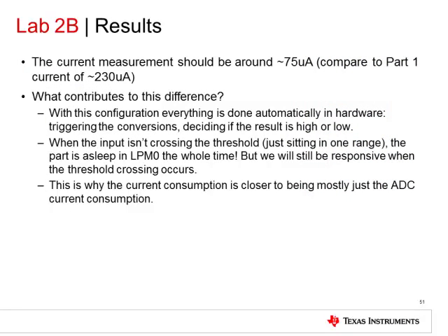So what contributes to the power savings compared to the previous lab? There are three significant factors that contribute to lower power. 1. The automatic timer triggers of the ADC to start conversion ensure that software is no longer needed. 2. Using the ADC in consecutive sampling mode to prevent CPU intervention. And 3, and perhaps most important, the window comparator logic that only provides interrupts when the ADC conversion result falls within a user-specified threshold.